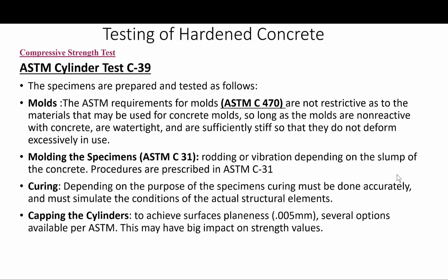Okay. The most common way of achieving the required planeness is to cap the ends of the cylinders, according to ASTM C617, with a suitable material. So 3 different capping materials are permitted.